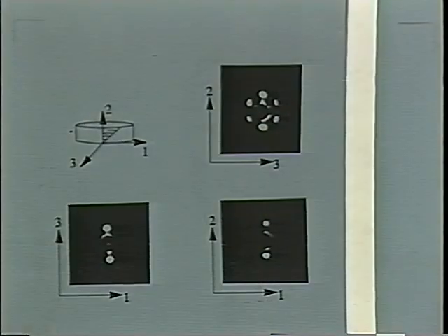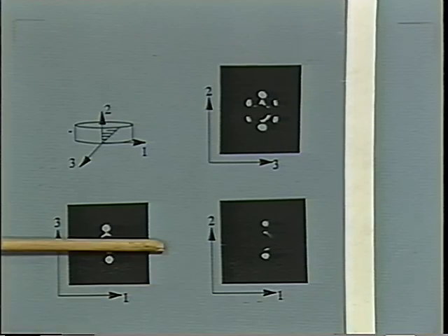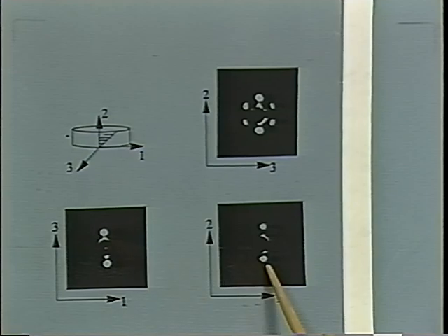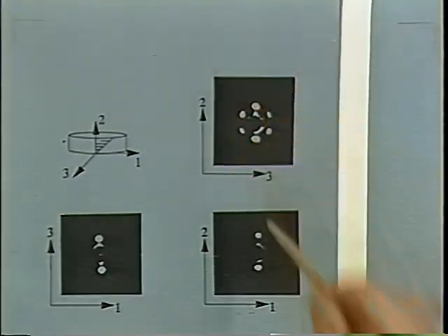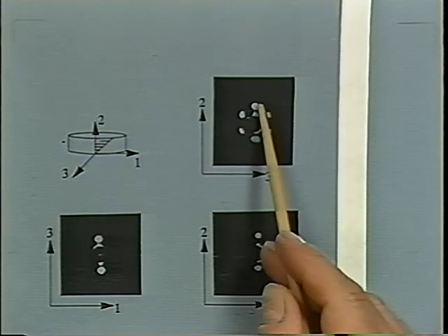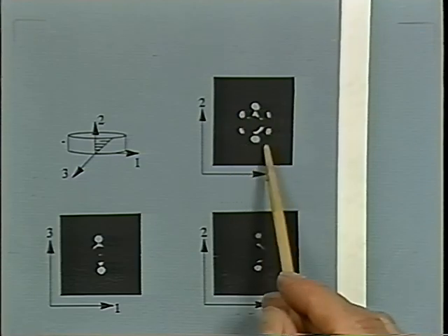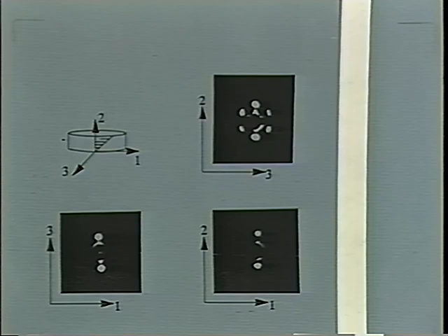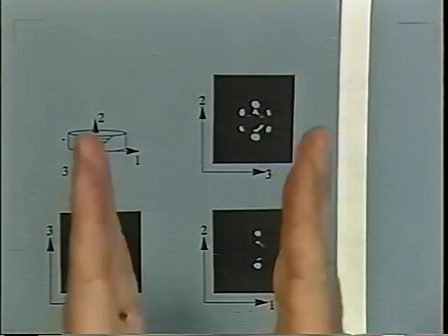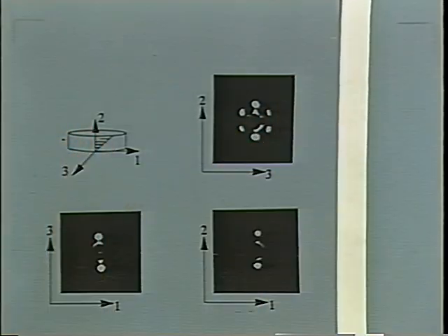But now I want to show you the X-ray patterns of that sample. You can see very high order. When you look at the cylinder sideways, the arcs are very sharp. And when looking at the sample in the direction of the cylinders, the arcs are also very sharp. And again, we have an alignment with the hexagon planes parallel to the shear planes. We are shearing the sample, and the shearing planes are really parallel to the hexagon planes of this order. The highest order we can achieve, and somewhere I had a micrograph, but that's also very, very uniform.